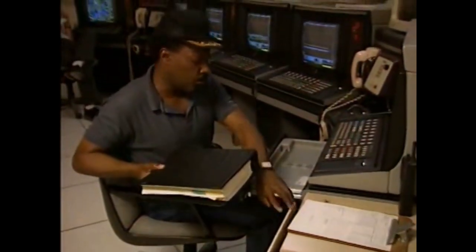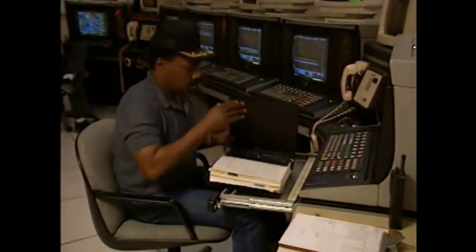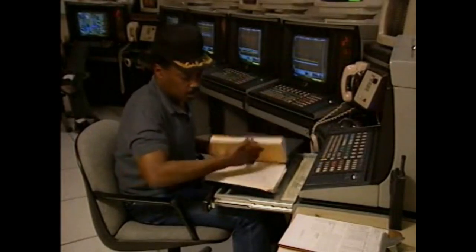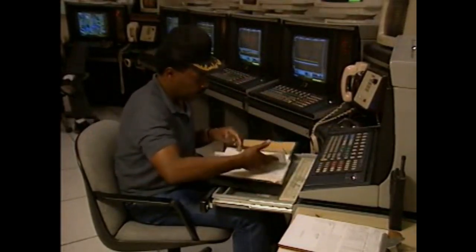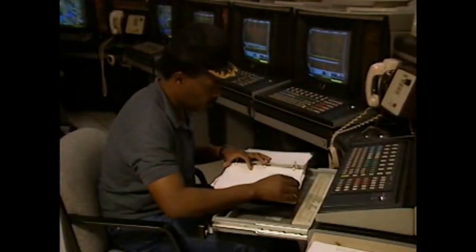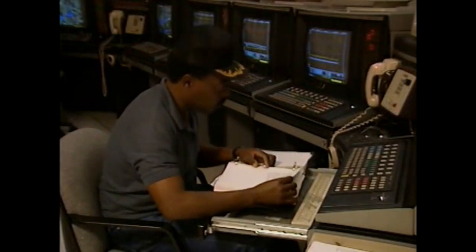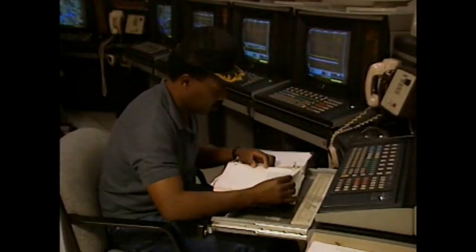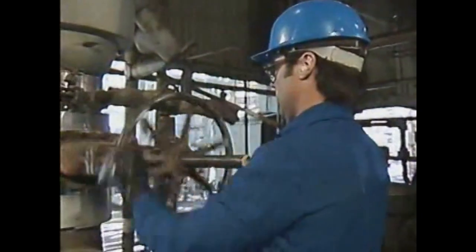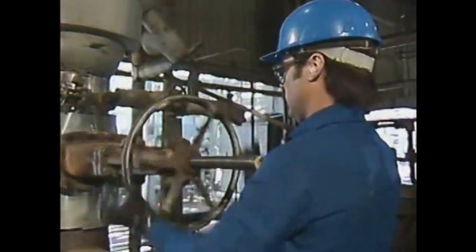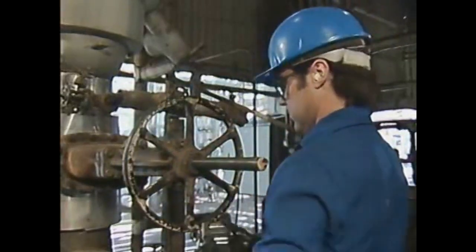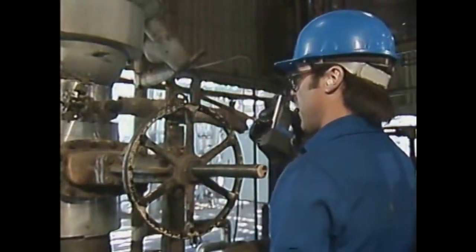Critical speeds are often identified in a compressor's operating procedures, and they occur when the compressor is at less than full operating speed. When a critical speed is reached, the ramp rate is usually increased to pass through the critical speed as quickly as possible. This action limits the time the compressor is operated at the critical speed and helps prevent damage caused by vibration.